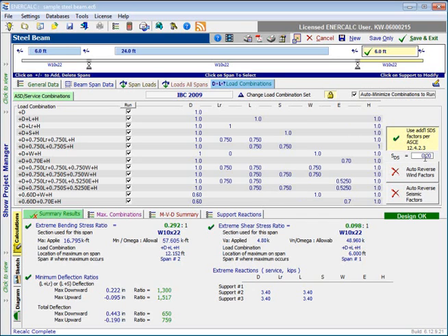It will automatically include the additional component of dead load in the form of a factor in situations where seismic load is a part of the load combination. So that can be convenient for properly evaluating your beam for seismic loads according to the building code.